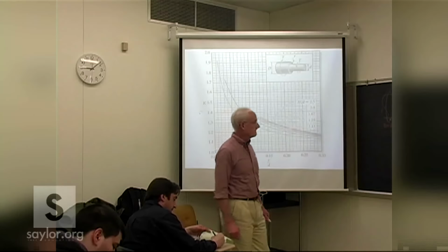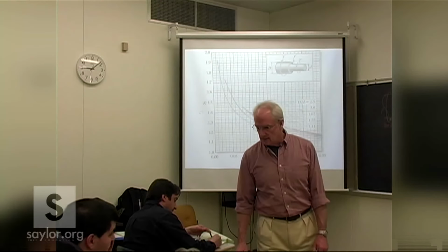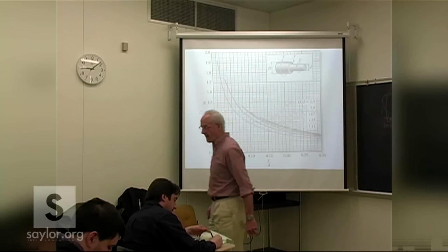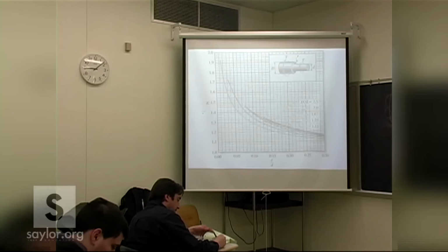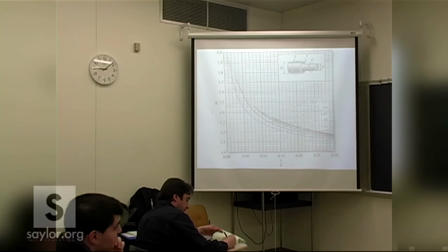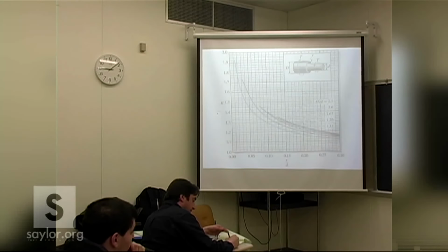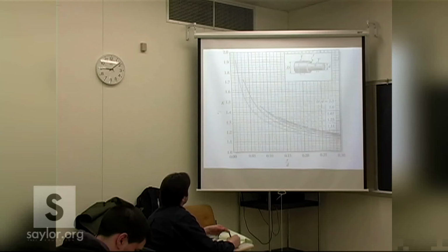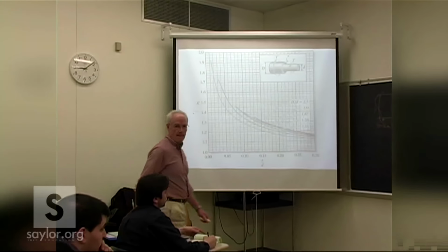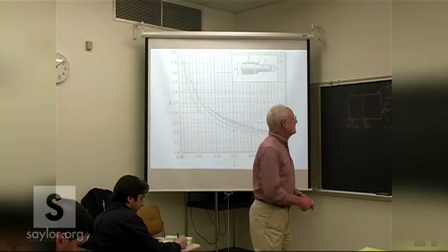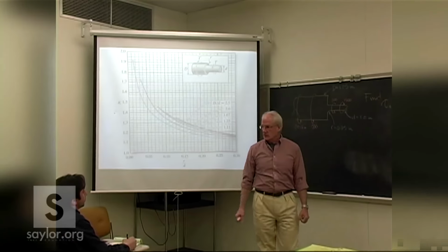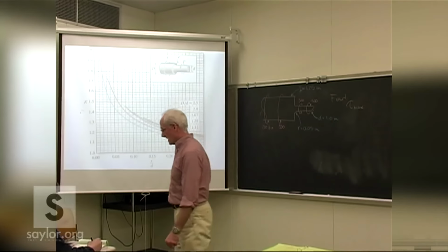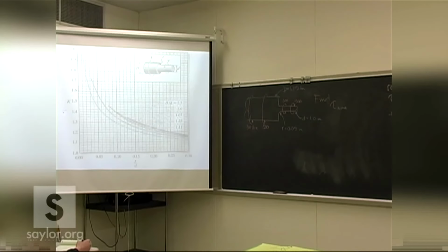So we have a shaft with four different loads on it, somehow. Gears are placed there, maybe even belts. Pulleys. What about the length of this? We only needed the length when we were looking at the angle of twist. Other than that, the length of any of this doesn't matter. It doesn't matter how far apart those loads are, other than that they're not right over each other.